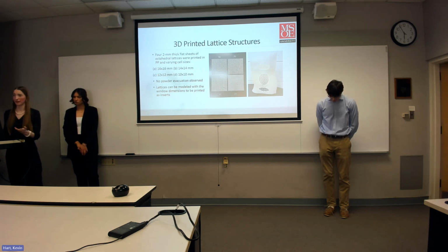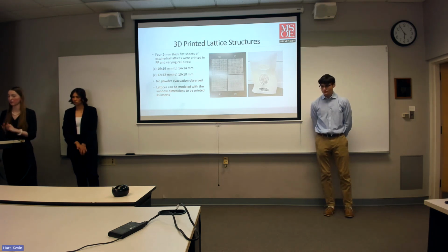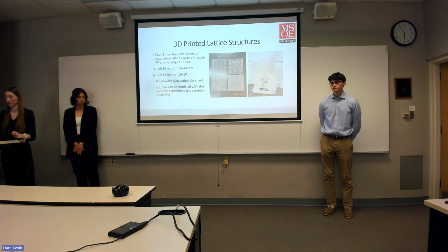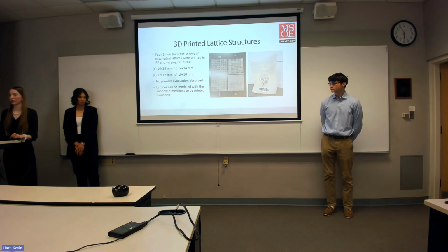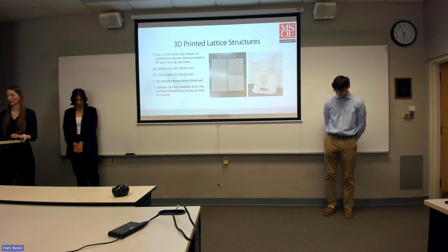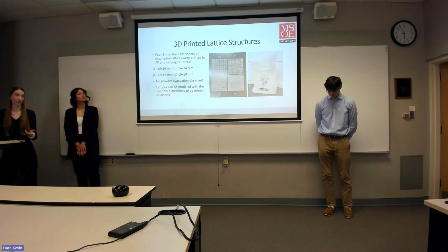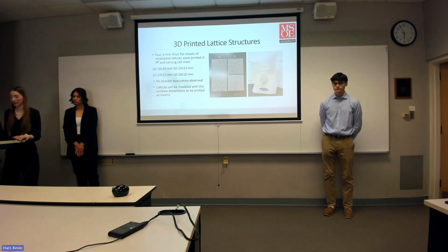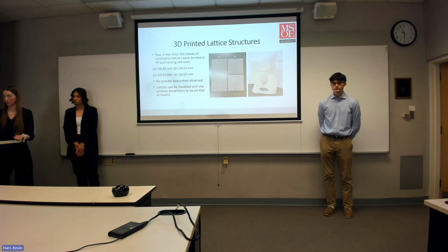These lattices were printed in polypropylene. They were very flexible, but still retained their strength and stiffness. They all printed successfully on the first try, and no powder evacuation was observed, which is a common issue with SLS printing in polypropylene. And with these 7 prototypes, we learned a lot about the capabilities of prototyping at RPC, the SLS printer, polypropylene, and working through the issues that we ran into to get a successful print. And these lessons learned, especially the STL mesh settings, will be applied to the helmet manufacturing process in the spring.